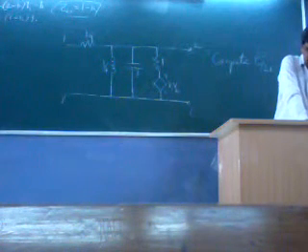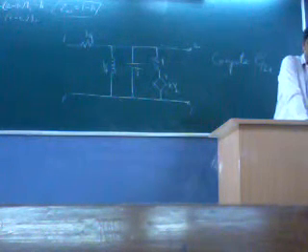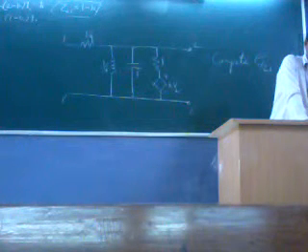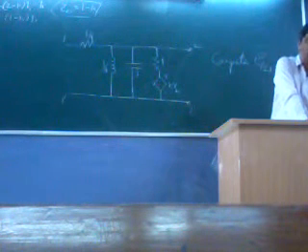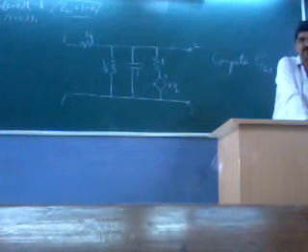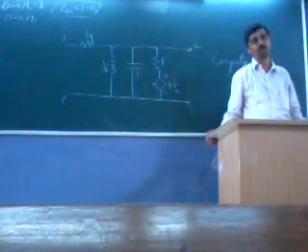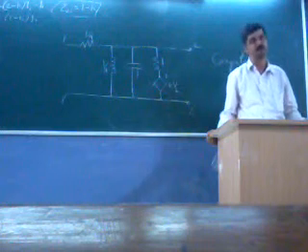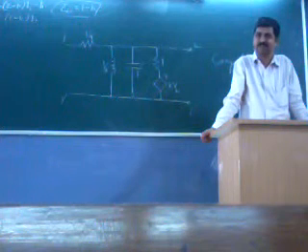If it is a completely resistive network, then there will not be any term of S. But we consider in general a network consisting of R, L and C. So all network functions, be it a driving point function, that is impedance at the input port itself, or a transfer function, be it transfer ratios or transfer impedance or transfer admittance, are a ratio of one polynomial in the numerator upon another polynomial in the denominator. Both are polynomials in S. Especially the denominator polynomial is meaningful for the stability of the network.